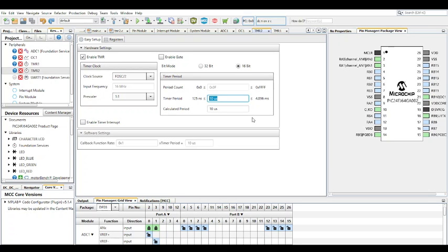You can't make the coefficients too high, they have to be super low, because you have to make the integral part super low, so it doesn't add on too quickly, because we're leaving some space for the capacitor, which is so big, to actually discharge. So having a switching frequency of 60 kilohertz and above is a big advantage.